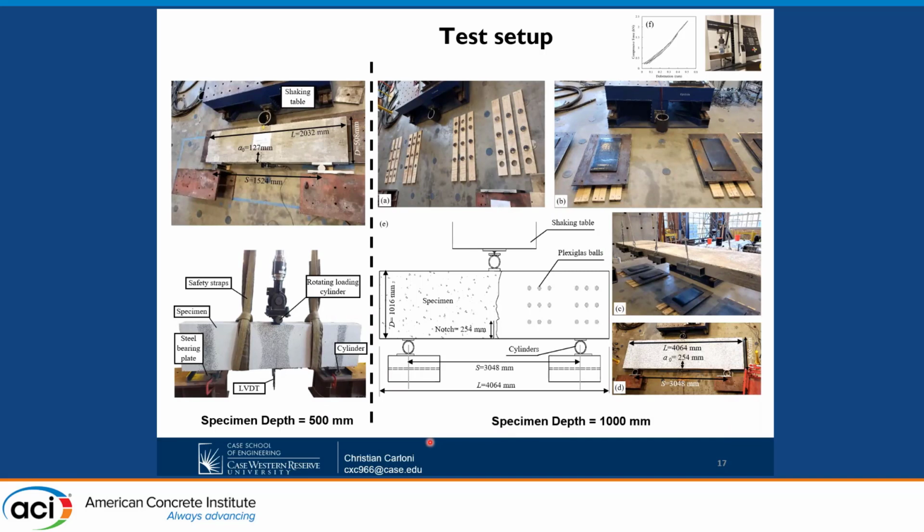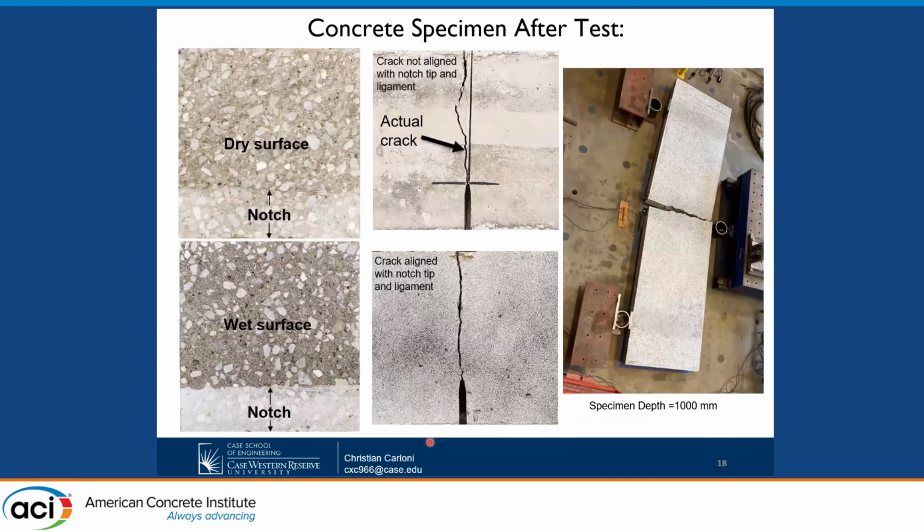The other one was coming in. So it was a little bit of a challenge. When we ran the test, we did check a couple of things. One, that the crack was not going sideways. Sometimes it does happen. There might be micro defects, and we wanted to make sure that the data were consistent.